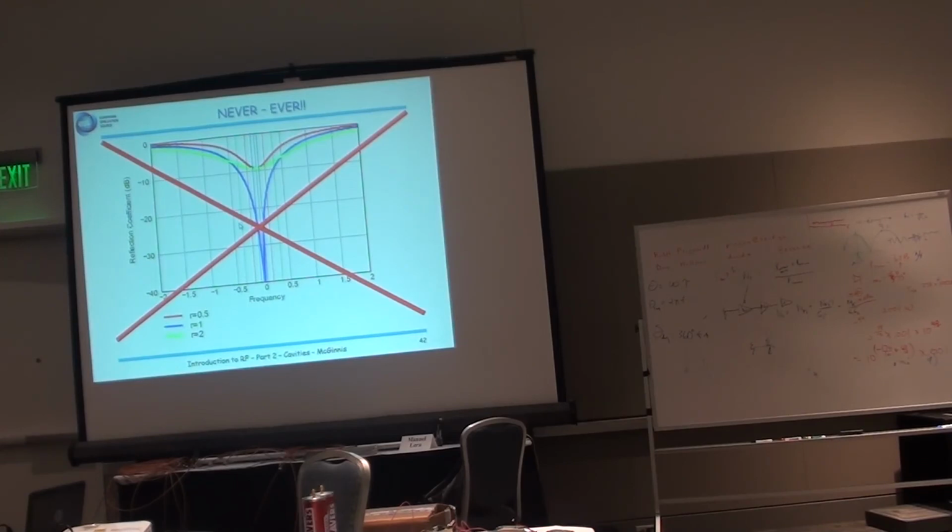You could do the sweep of S11, but you still need one extra piece of information. You need to look at the Smith chart to measure what the coupling value is. But if the coupling value is so small that it's no longer affecting your result, then this is a flat line. If the coupling value is so small, you never get any energy into the cavity. It doesn't have to be 0, it just has to be small enough that it's not affecting, but then you still have to know how far from 0 it is. You can work out the math. We'll probably go after it later, but really it's a dangerous way to do it. You can do it, but you have to use the Smith chart to get the coupling value. And since you've already gone to the Smith chart, just do it the right way.